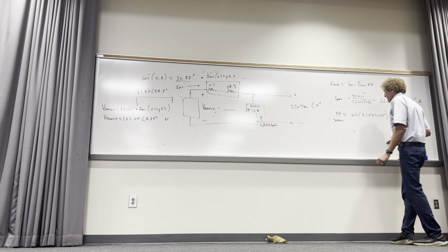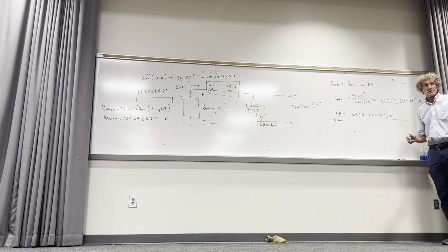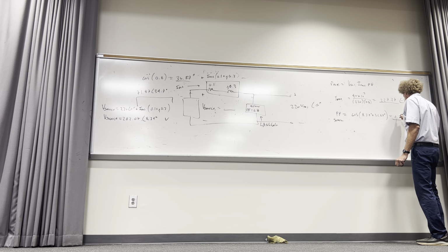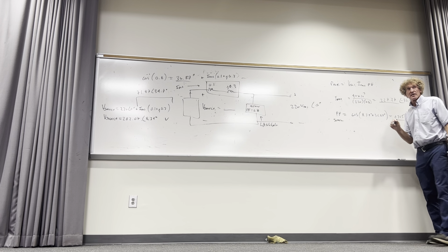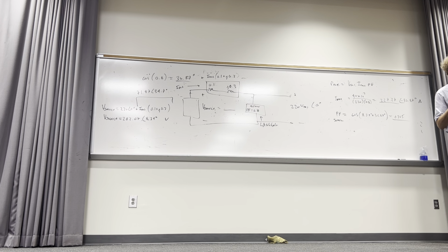Now what's that power factor going to be, class? 0.705. Is that right? How many got that? I hope it's right. All right, is it leading or lagging? Lagging, right? Look at the angle of the voltage and compare it to the angle of the current. The current angle is less than the voltage angle. Do y'all agree with that? And that's really what it's about. Okay. That problem, I think, is straightforward. Do you have any questions before I move on?